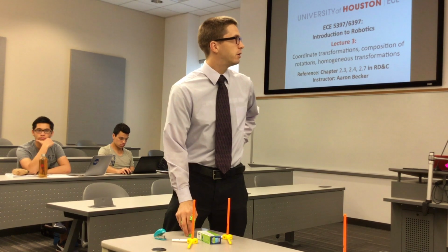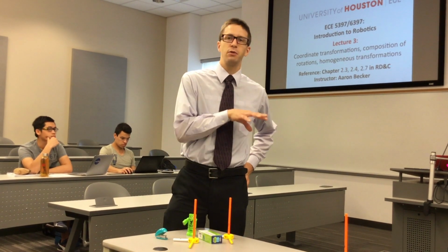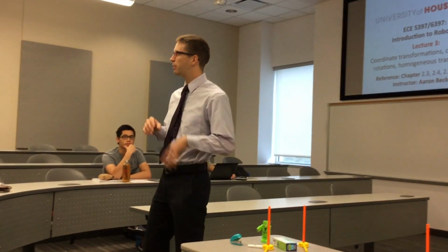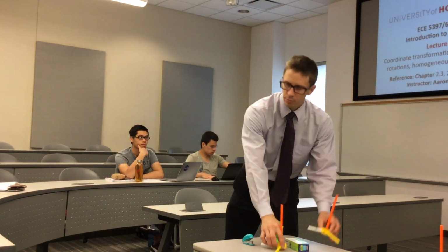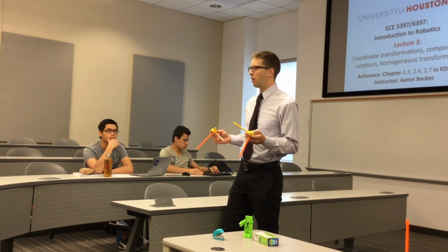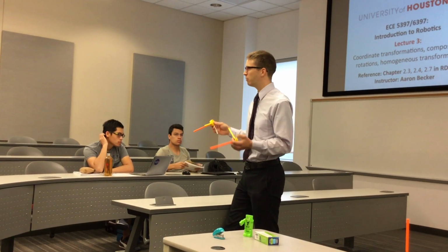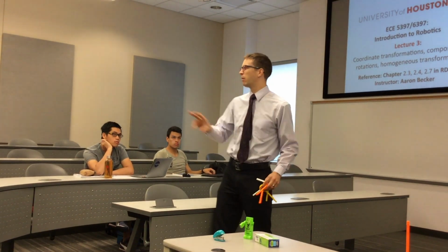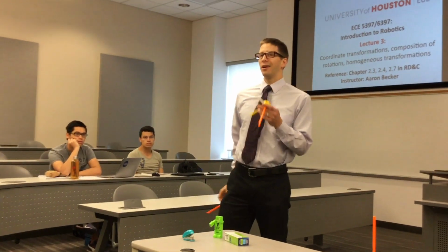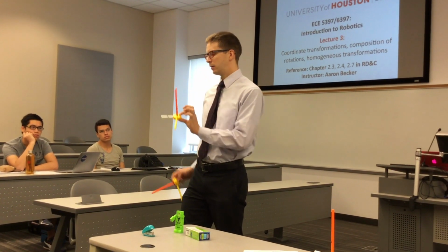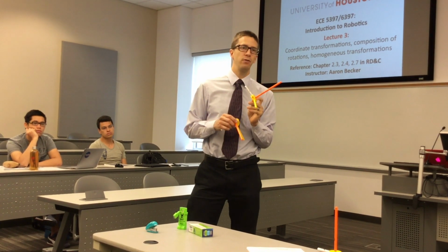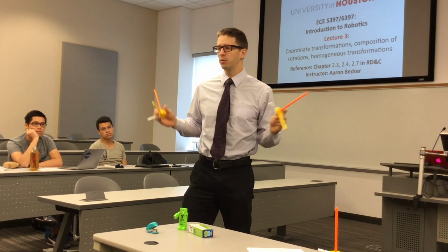So today we're going to jump into coordinate transformations. How do I transform from one coordinate frame to another? And how we're going to do that is we're first going to talk just about the rotation aspect. So we're going to assume, remember, a rotation is just like a vector. A vector just tells you a direction of movement, and so we can move that vector around anywhere that we want, but it's always pointing at the same orientation. And so what a coordinate frame is, it's three vectors that are bound together so they're mutually orthogonal, and we use a right-handed coordinate frame. So these are right-handed coordinate frames. We're going to pass these around.